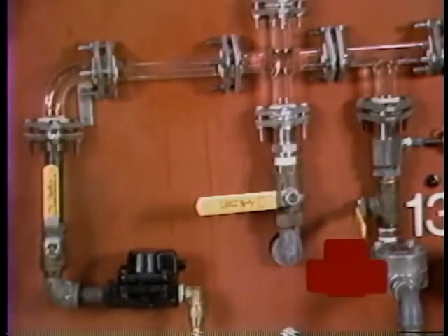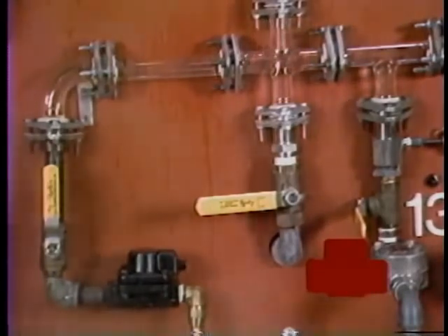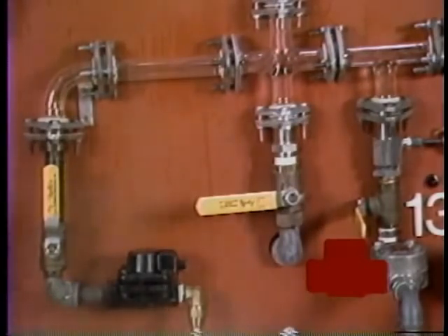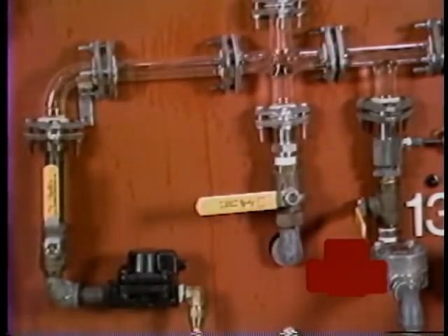The service life of the disc trap is expected to be short. Under heavy loads, the disc trap backs up the condensate, and on light loads, the high velocities through the orifice, as well as the violent impact of the disc on the seat, make the trap especially susceptible to wear.